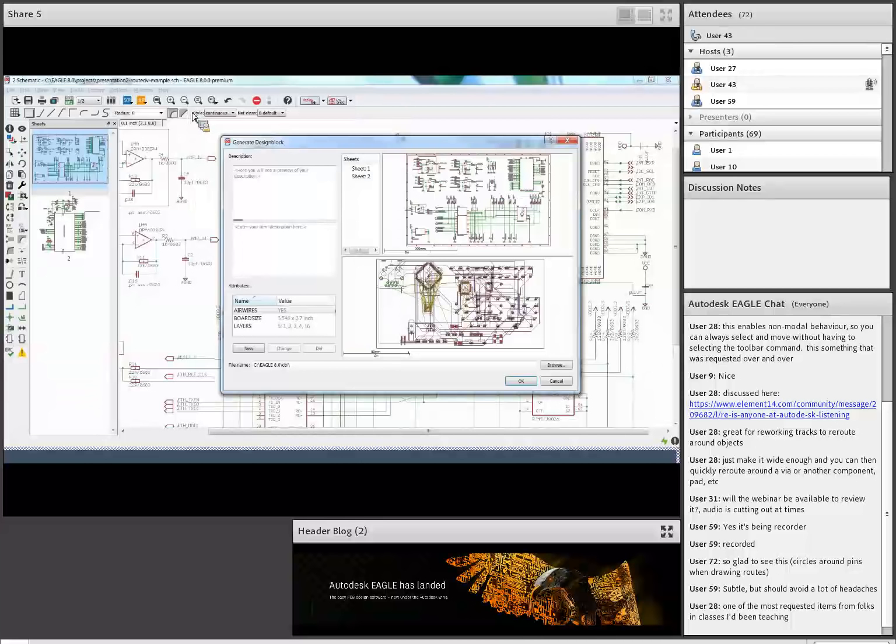Maybe you might create your simple schematic with a board with a particular application, design application you wish to use, and save that as a design block. That way you could reuse this at a later time with a future design or within the same design. Okay, so this is the easy one when you're going to save the entire design as a design block.